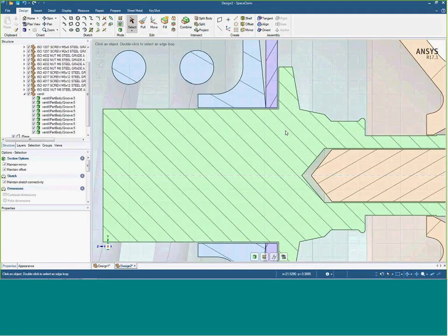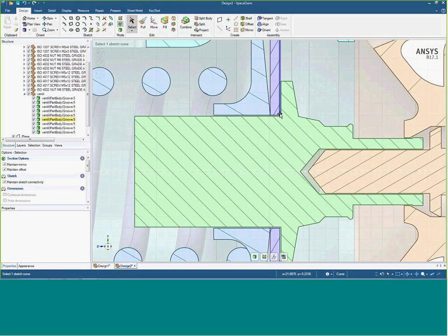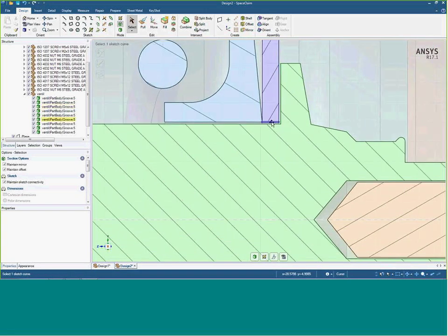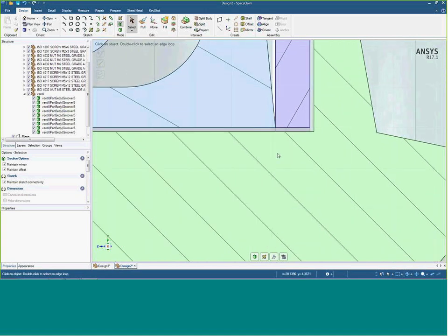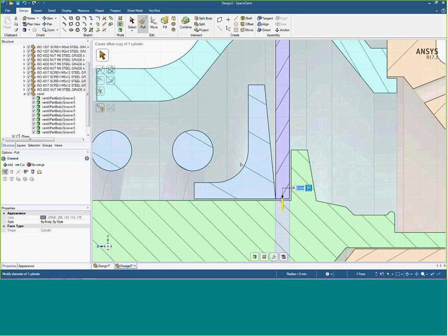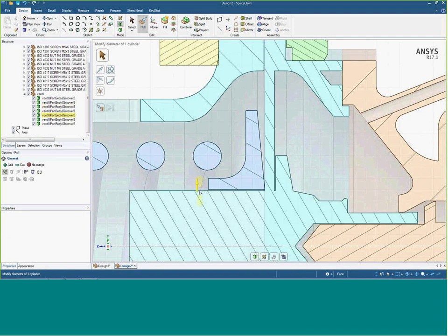If we look down at this centerpiece of this valve in green, we see that there's a bunch of gaps. So this is kind of floating in space. We need to put contact in here if this was a structural problem, or maybe we try to close these gaps. These parts are line on line. We could do something like that very easily with the pull again, which is, just grab the edge right here, and we can pull this up to the diameter of this part right here.